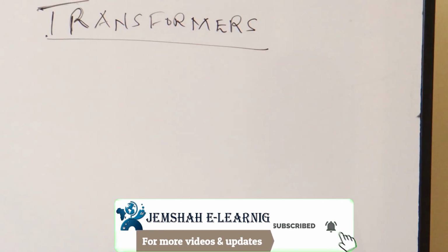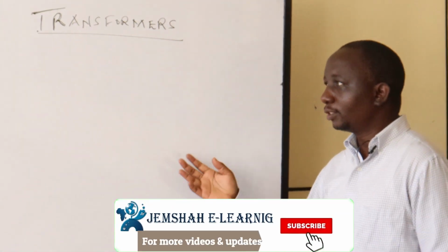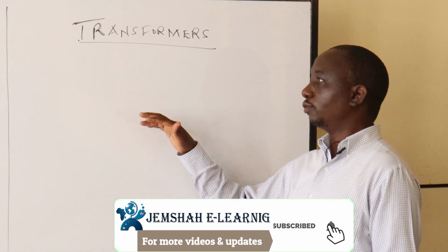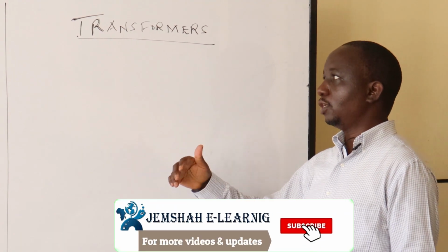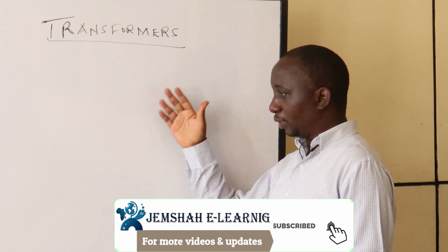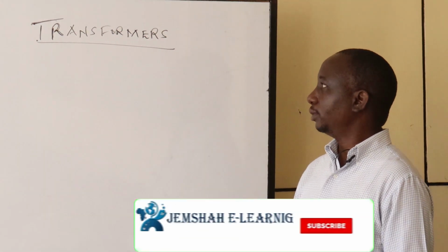From there, you're supposed to know the applications and some measurements that we do in transformers in terms of the iron losses and the copper losses, or the open circuit losses, or the short circuit losses. So those are the areas we need to measure on.